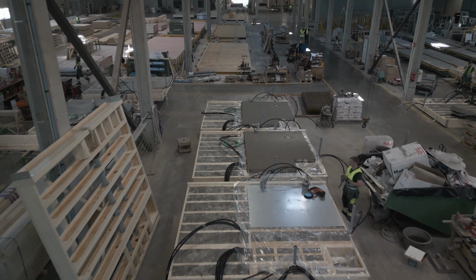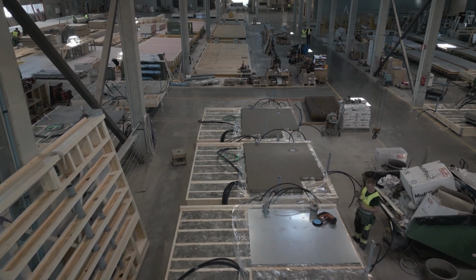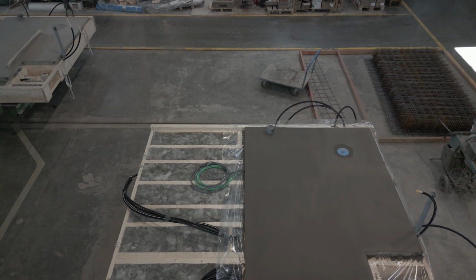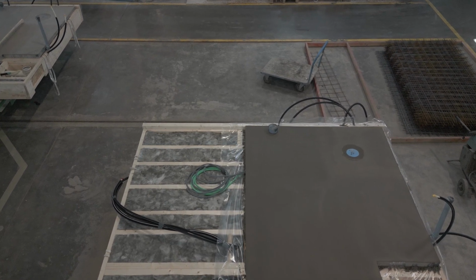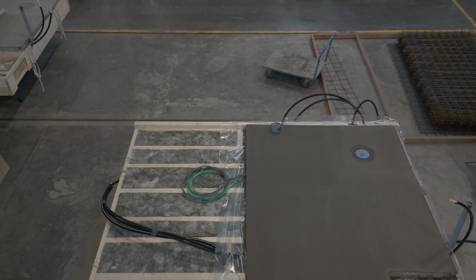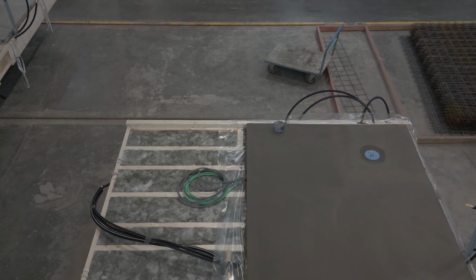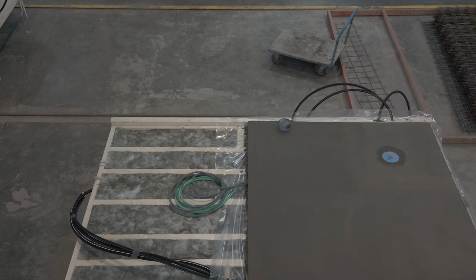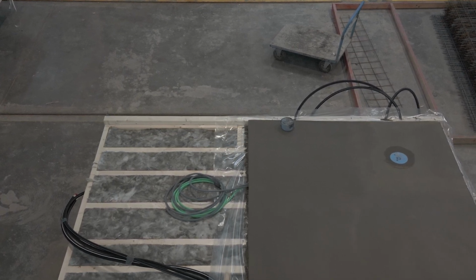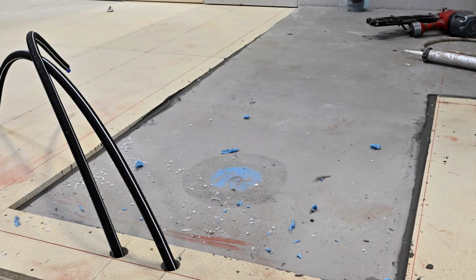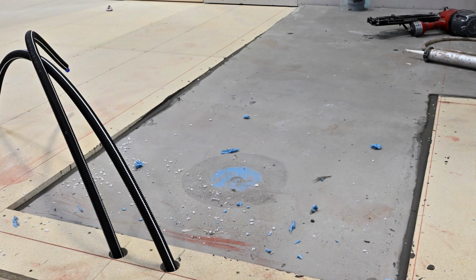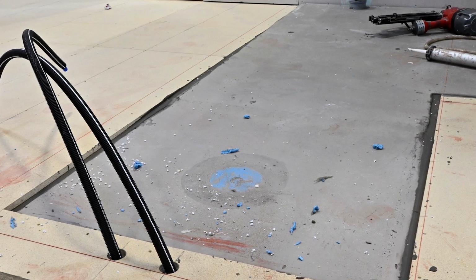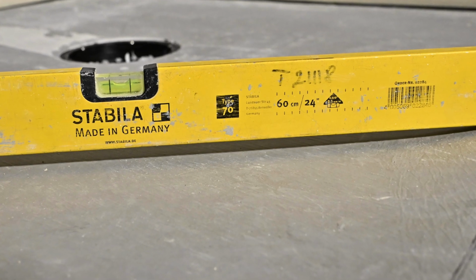The floors of wet rooms in modular buildings are typically constructed on either a poured concrete slab supported by a wooden frame or on prefabricated high-density wood fiber boards with a ready-made fall. A general rule is that the subfloor must be completely rigid and must not deform under heavy loads. The floors of wet rooms must have a gentle slope towards the drain in the general area with a steeper slope near the floor drain to ensure quick water drainage.